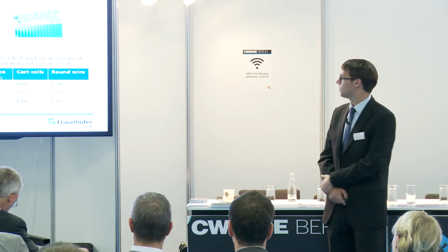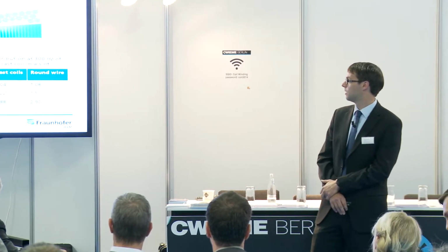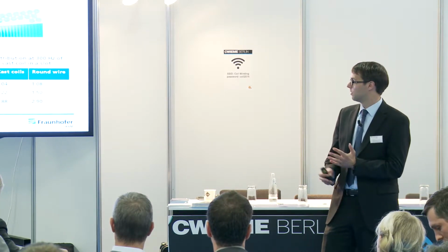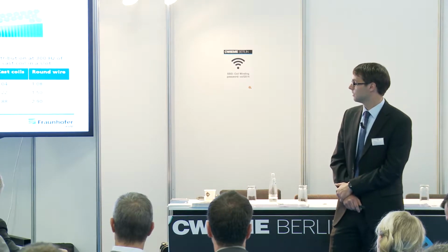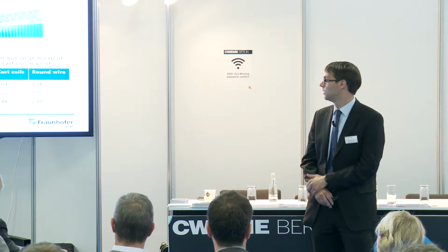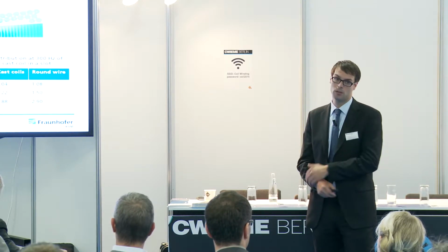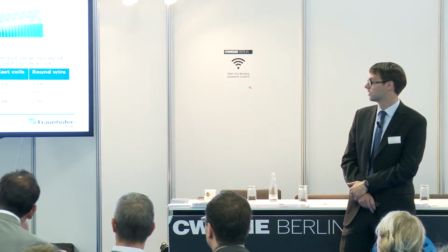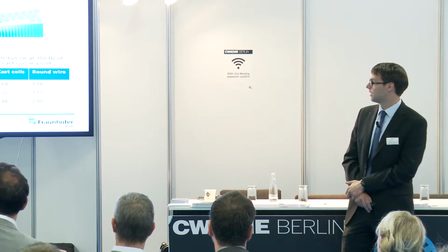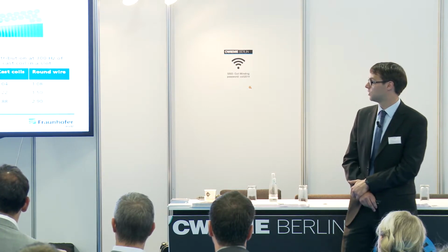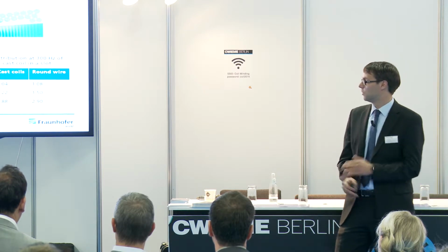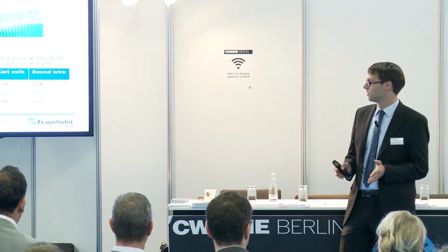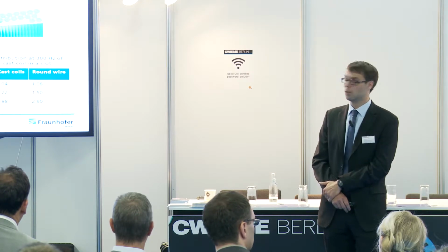We see that on the right side, we have a comparison of 2 coils with same turn number. One with a flat conductor arrangement, one with round conductors wound. And with the flat conductor arrangement, we get from an electromagnetical point of view the optimal arrangement. So we have very low current displacement effect compared to normal wound conductors. And of course, the bending radius at the end windings from the electromagnetical point of view has some advantages too. We get the possibility to increase the distance from the housing, so we can reduce eddy current effects in the housing due to less leakage fields.